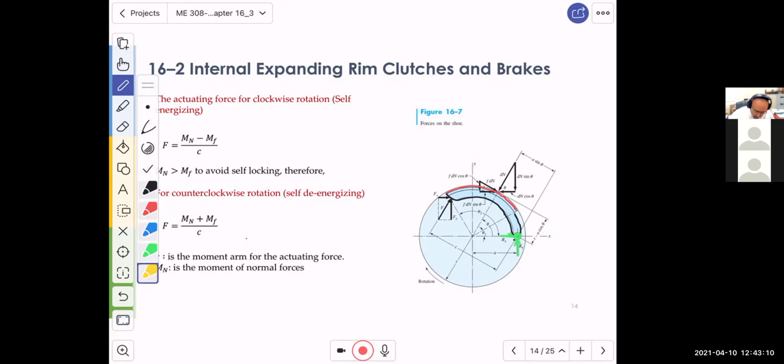And we are going to actuate it. So the yellow arrow is the actuating force, which is going to be inclined. And yes, you can know the angle and you can resolve this force into X and Y. There's no doubt about it. The reactions in here, we don't know them. We will just assume X and Y again. And of course, this is allowed to rotate. It is not fixed. There is no reaction moment.